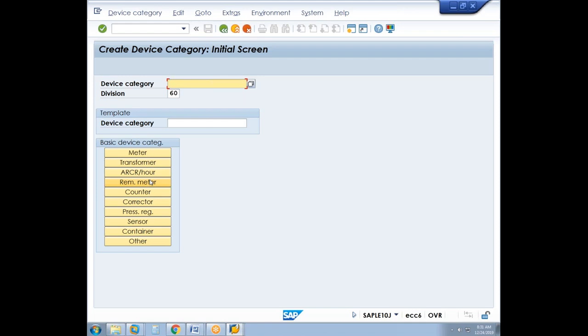Okay, that means the street lights are switched on and off based on the signal sent from the ripple control receiver. And in some countries, they use it for load balancing. Whenever there is suddenly a surge of power in a particular area, using the frequency imbalance, the ripple control receiver will send a signal. It will switch off the supply to the area, and then after the loads are stabilized, it will resume the supply to that particular area.